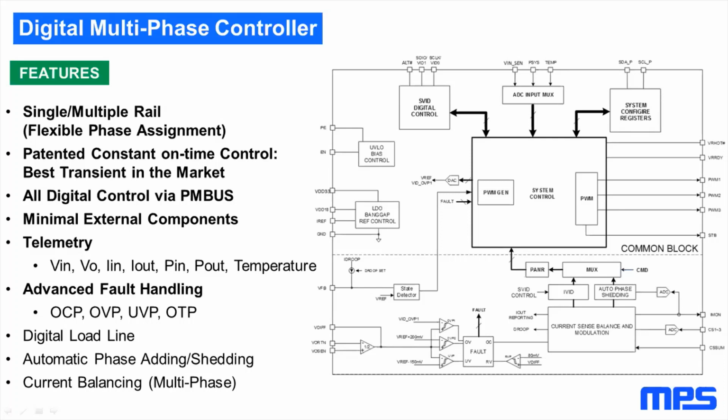There are several protection features implemented too. There is an overcurrent protection. Exactly, it is a configurable per phase valley current limit and a configurable average rail current limit to protect the design. Configurable in this case means you can set either the protection value in amps, but also the protection behavior. So for example, you can retry or latch off if a fault happens or simply ignore the fault. Ignore does not make sense to set permanently. It sometimes makes sense to set it during debug or bring-up sessions.